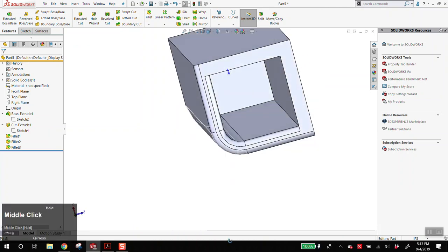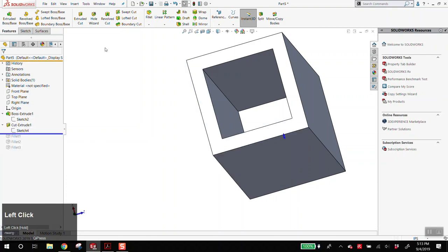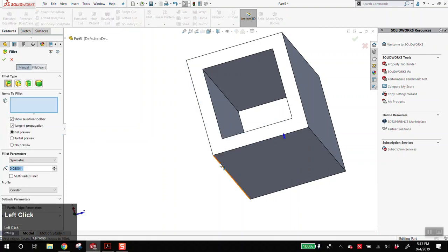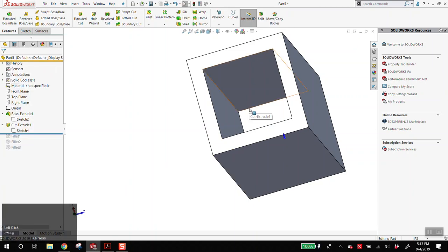That's a good question. Typically, I would do inside out, especially if you're doing a cavity like this. The reason for that is if I were to go ahead and do this outside fillet first, and again, just put in a big number here, it's going to fail a lot quicker because it's going to run out of material when it hits that corner. Does that make sense? But kind of a trick question. Really, the best way to do this cavity in this instance with what we're trying to do would be with a shell, but we'll learn shells later.